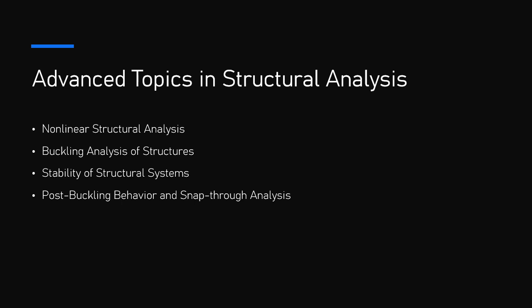10.4. Challenges in nonlinear structural analysis. 1. Computational complexity. Nonlinear analysis requires more computational power and time due to the iterative methods and the need to update the system's stiffness matrix after each load increment. For large-scale structures, nonlinear analysis can become computationally expensive, requiring high-performance computing systems or specialized software.